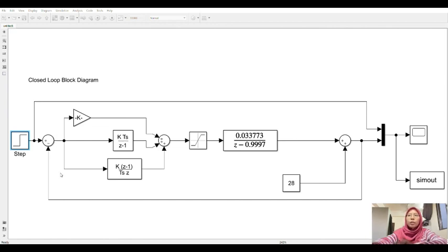And then for our gain, we put 2.23277, which we already calculated in the first part, and then here we get the discrete time also, and we put 0.00223, and the discrete derivative we put as 558.639.